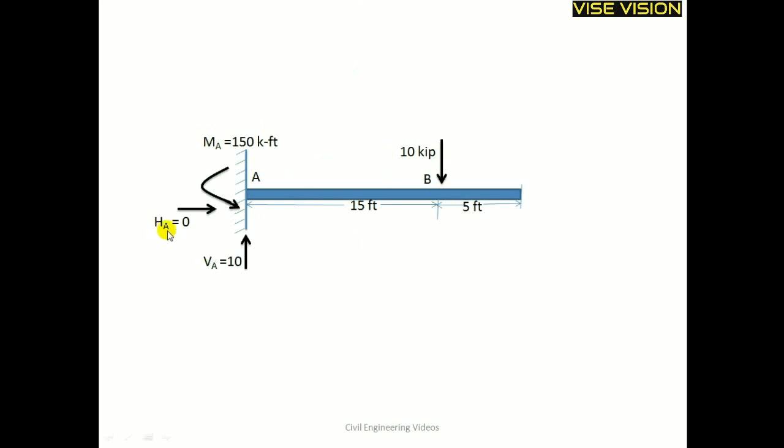Now the horizontal reaction, you can see it is 0 because in this cantilever no horizontal force is acting. If any horizontal force were acting over here, this horizontal force would be directly equal to the horizontal reaction.